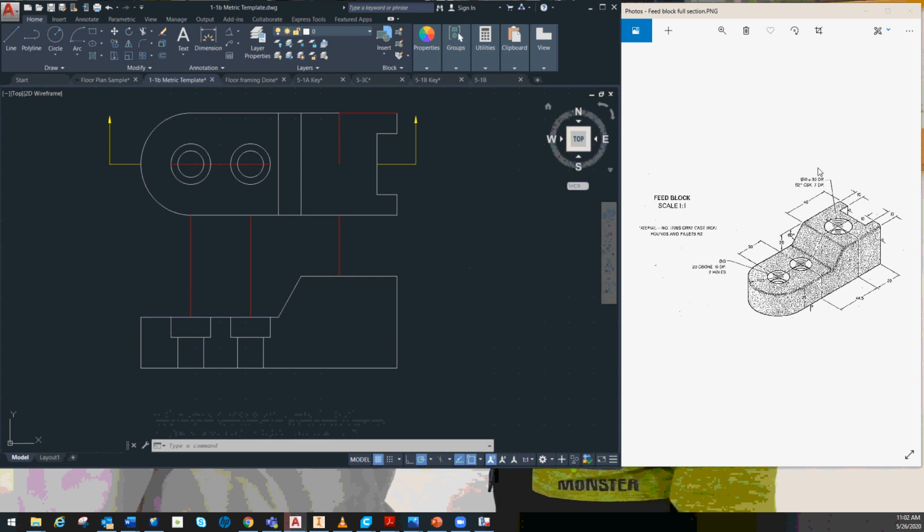So let's start with this 10 diameter, 30 deep, because if you were actually making this out of wood or metal, that's usually what you'd start with: you'd get this hole drawn. So let's now go back into a construction layer, and I'm going to come down the middle here. We're going to go down 30 units, and it's going to be 10 diameter. So I'm going to go 5 this way and then back across. This is just a construction marking.